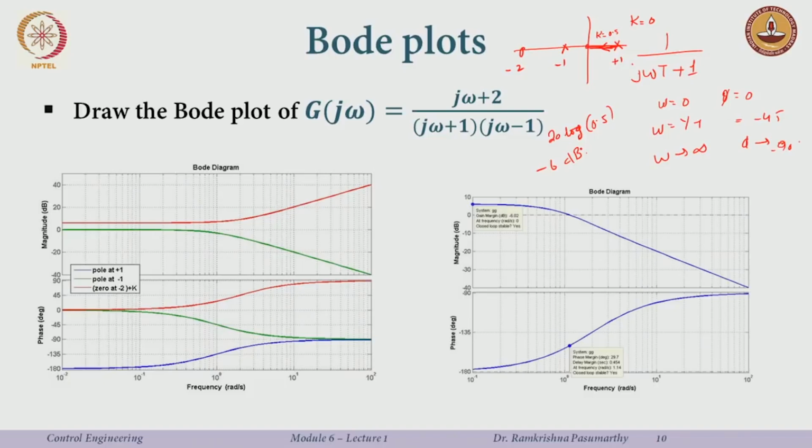If you remember, last time I said these are systems which have negative gain margin, even in the Nyquist plot. So, look at how the Nyquist plot looks. This was minus 1, this was minus 2. For a system, when we sorted out the Nyquist arguments, we said if this was A, then 1 over A was the gain margin. So, if you increase the gain by a factor of 1 over A, the system was stable. Here, what I am doing is decreasing it by a factor of 1 over A. This is 1 over 2 in the negative direction, and therefore I have this negative gain margin of minus 6.02.